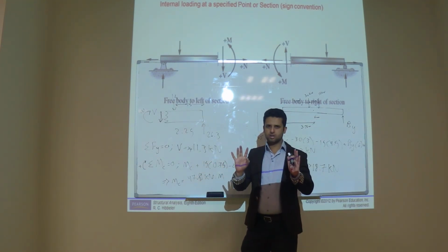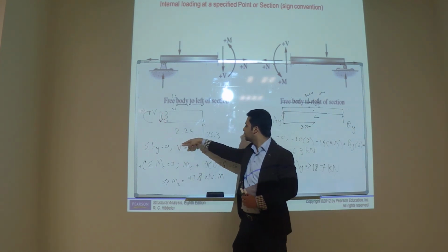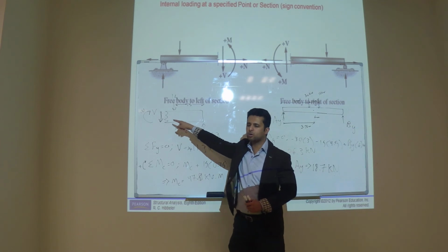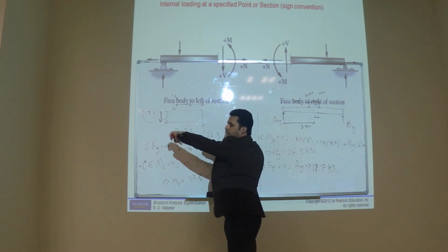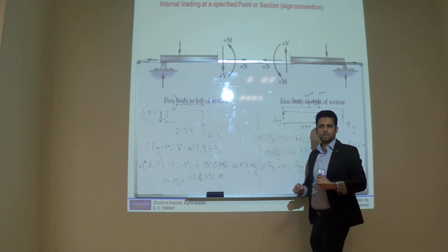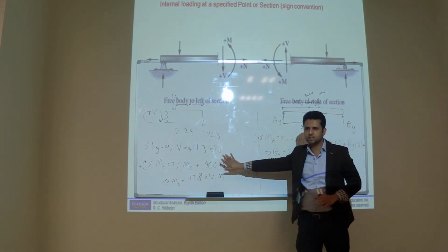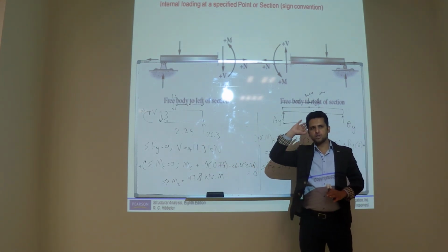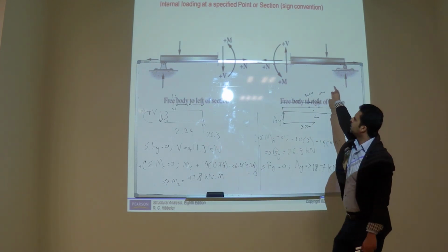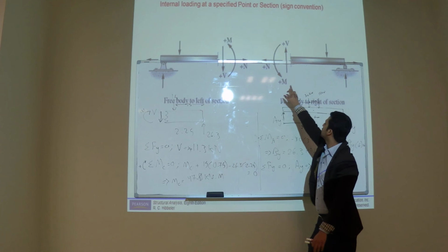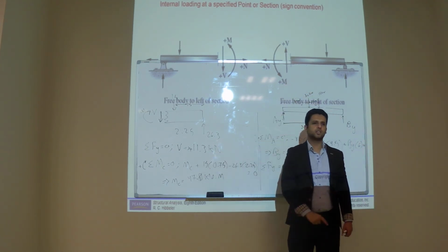If you do not want to consider the sign convention, just keep this thing in your mind because it is producing counterclockwise. See this shear, it is negative. So, teacher, maybe we add a note like, you should tell here it is negative shear. Okay. Either you should do it by your common sense or you should assume these directions during the question. You should assume the positive shear, this one. If you get the negative answer, it means the shear is negative.